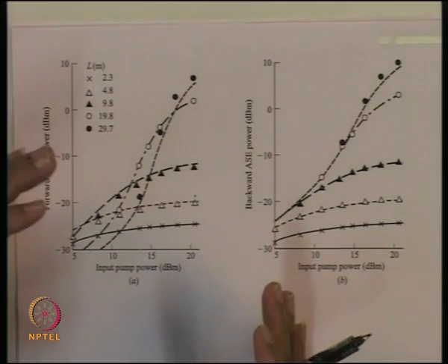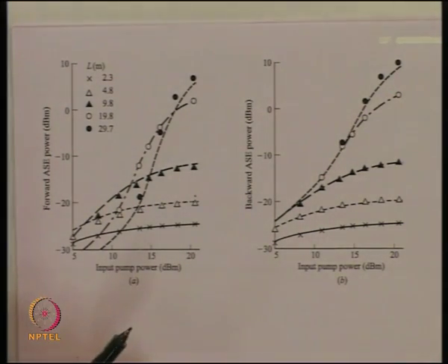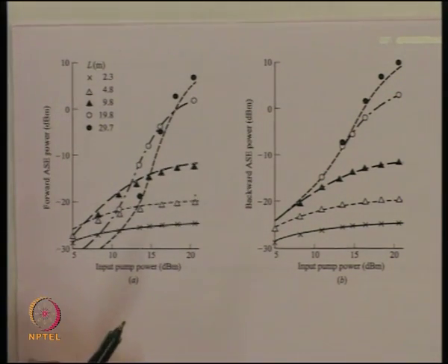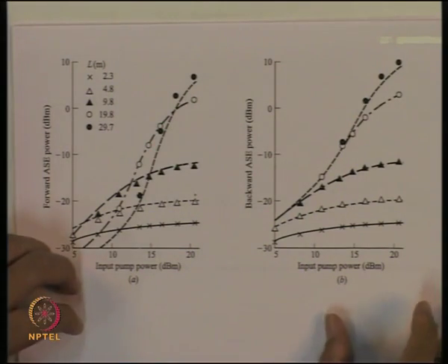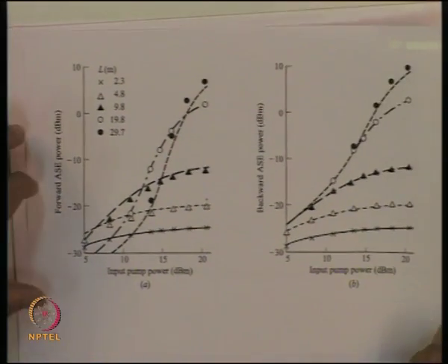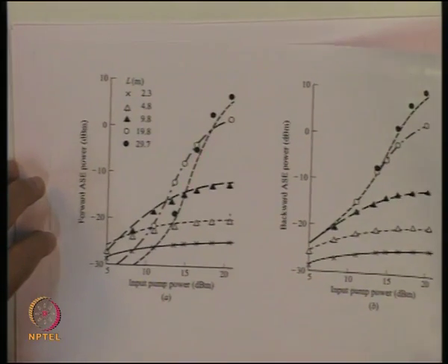So this gives you essentially the relative difference between the ASE which will be created in the forward scheme and the backward scheme. Now what does the ASE do further? When the signal reaches the detector, originally the ASE is a noise, which is the broadband noise generated inside the EDF, and it reaches the detector.